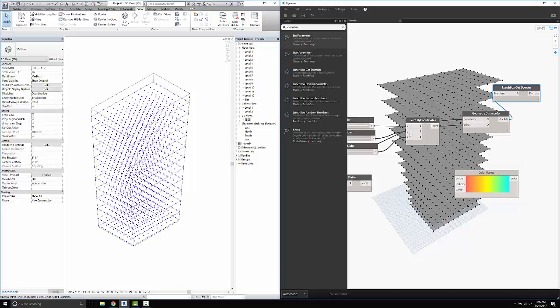oh, it's still split out into lists. So as I had kind of thought, we need to flatten. Oops, that's our problem. I did not use the flattened version of our geometry. So I'm going to assign that flattened geometry. There's our list. And we have now the Lunchbox domain is giving me the lowest number, which is 0.